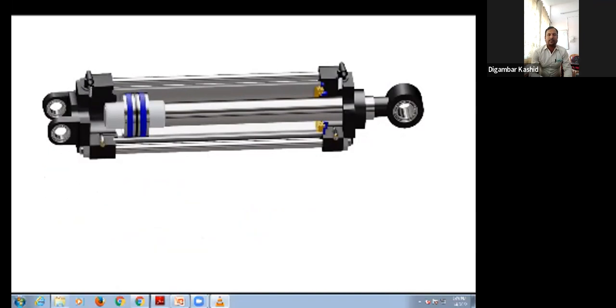Frictional losses on the interface of different surfaces also need to be considered while designing a pneumatic cylinder. The diameter of the rod and the length of the stroke are also determining factors for the capacity of the actuator.